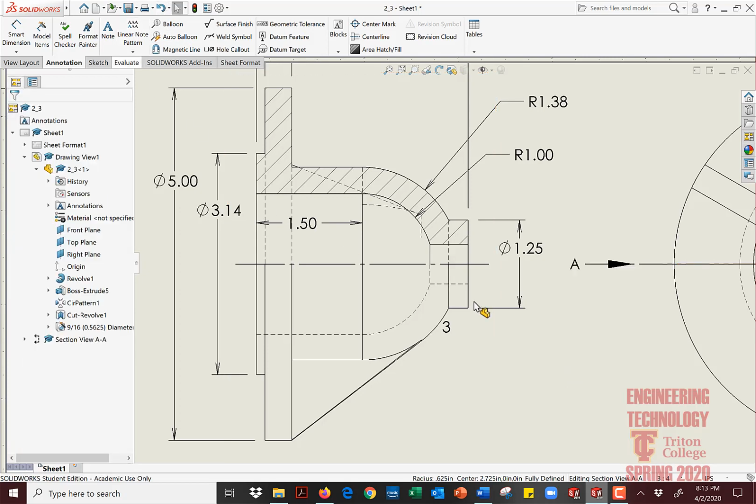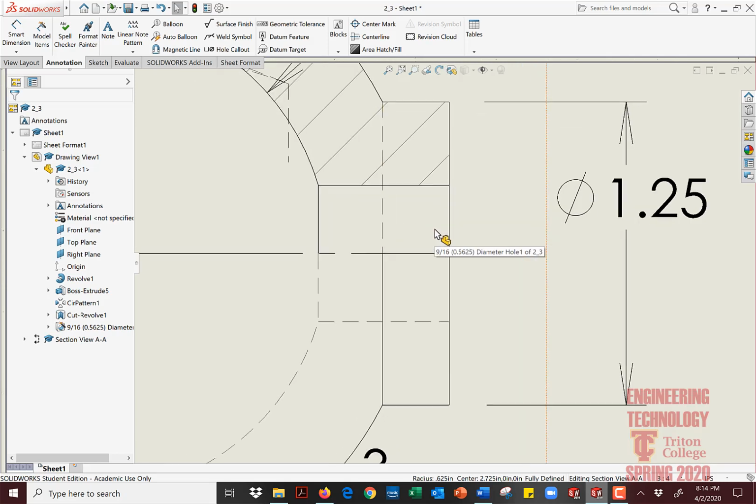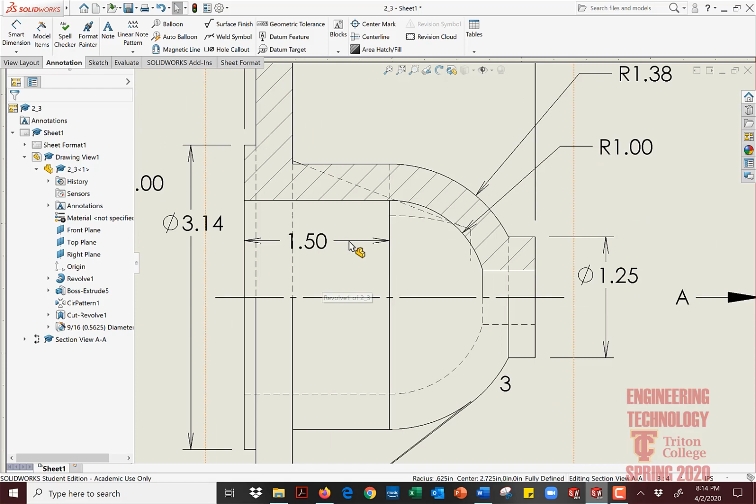Okay? For example, here you have an example where part of the line is a solid line and part of the line is a hidden line. See that? This is a perfect example of where you're going to get all or nothing because the product doesn't understand what you're doing. This half of the hidden line is really symbolic of this solid line in front. You cannot surgically just pick this half and turn it off. The only reason I was able to do it with these was because it wasn't attached to anything. That's also a visible line.